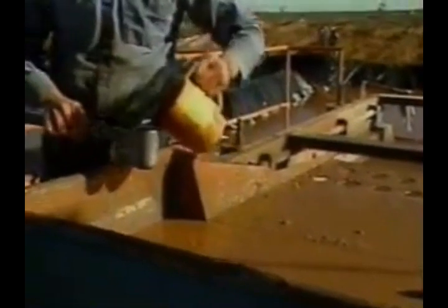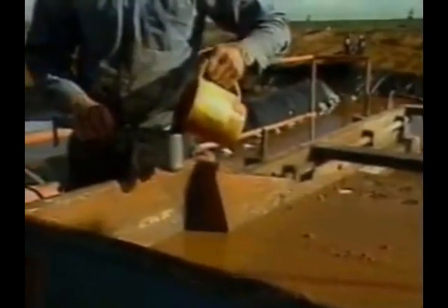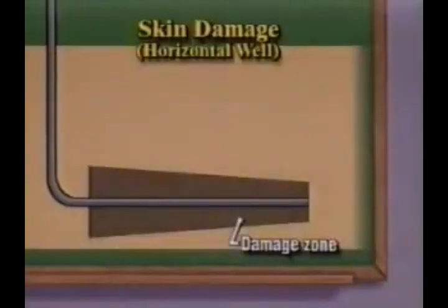Borehole instability is another potential problem, particularly in the bend section of the hole. This requires careful attention to the mud weight and to the interactivity of the mud components with the minerals in the formation. Formation damage is an area of concern that's magnified in horizontal wells because they expose more of the formation than do vertical wells. Special attention to this aspect of drilling fluid design is, therefore, critical.